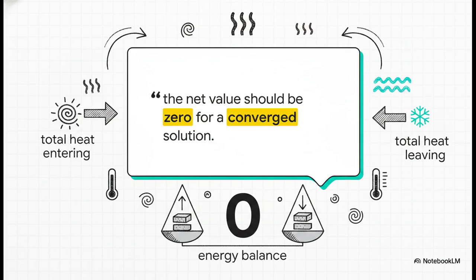Look, it's one thing for a simulation to just say it's finished running, but you have to verify the physics yourself. If the total heat entering your simulated system doesn't essentially equal the total heat leaving it, your net value isn't zero. And if it's not zero, that means your digital reality hasn't obeyed the first law of thermodynamics yet. So always check the energy balance.